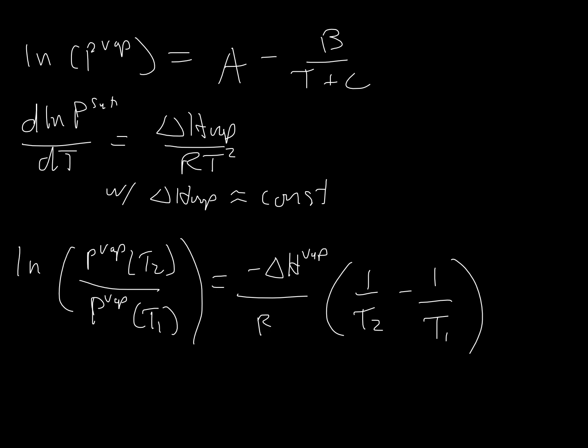And the reason why they chose a polynomial fit is because it is very easy to integrate, because integrating the heat capacity is basically its job. But in terms of the Clapeyron equation and how it relates to the Antoine equation, write that here. Right, it has a functional basis. It's exponential. So your uncertainty of how accurate your vapor pressure fit is going to go down, but it's not going to explode catastrophically necessarily.